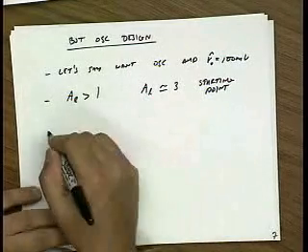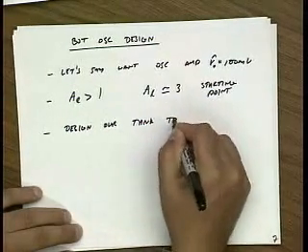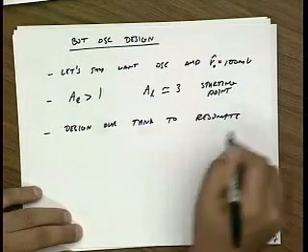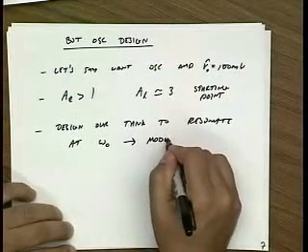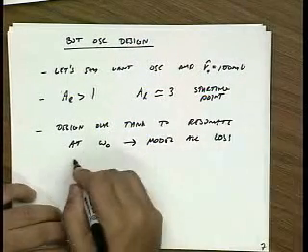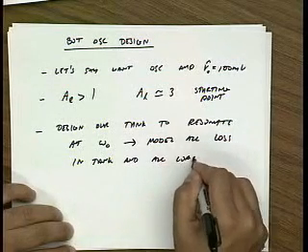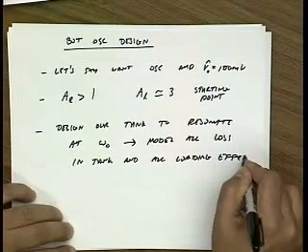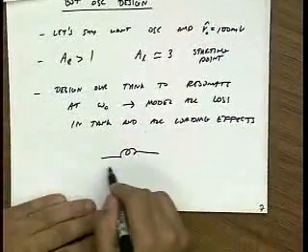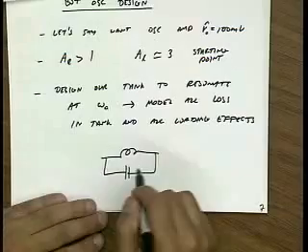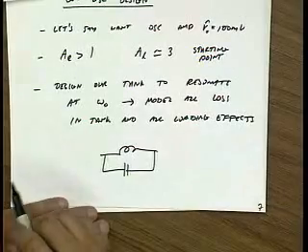Okay? So the next thing we do is we design our tank to resonate at omega naught. And here we have to be very careful to model all the loss in the tank and all the loading effects. The tank is something sacred. This is my LC tank, and you want to keep it as clean as possible, so avoid putting anything on this tank that would de-Q it.